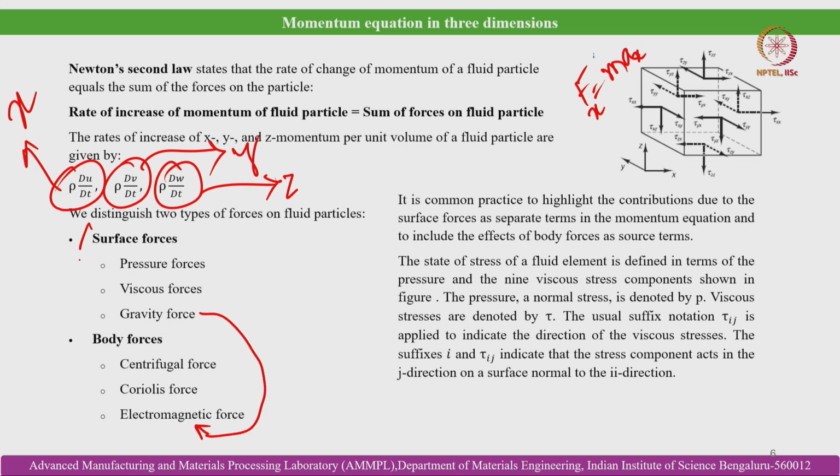So, surface forces are limited to pressure forces and viscous forces only. So it is common practice to highlight the contributions due to the surface forces as separate terms in the momentum equation and to include the effects of body forces as source terms. How we are arriving at that treatment I will be discussing next.